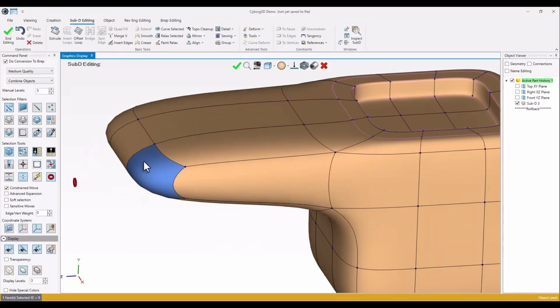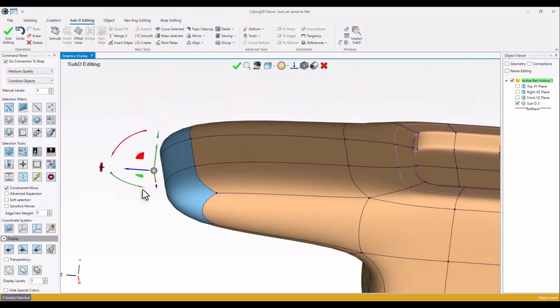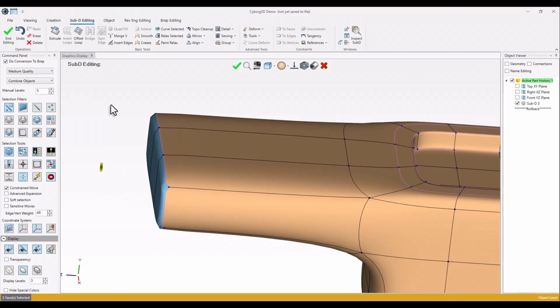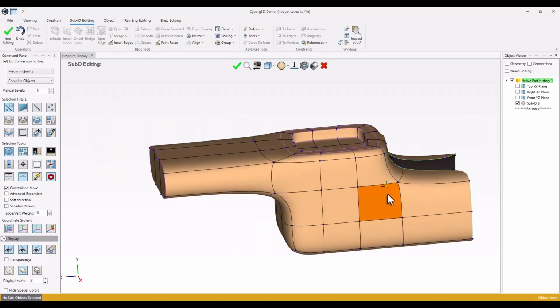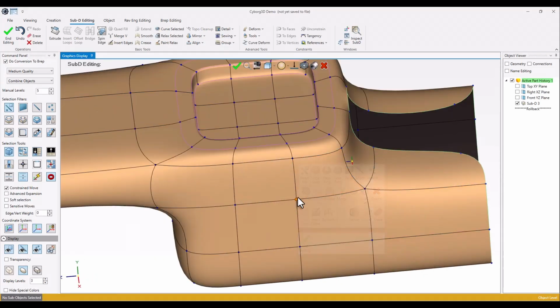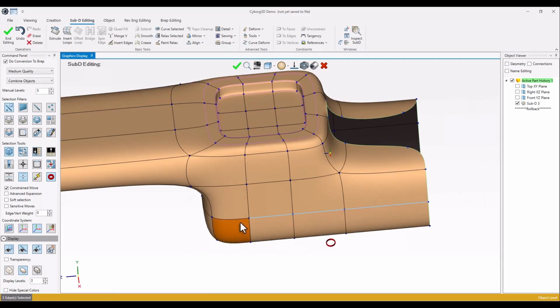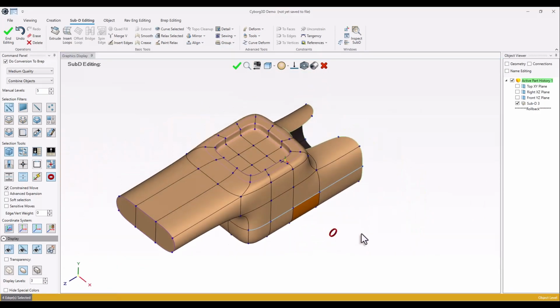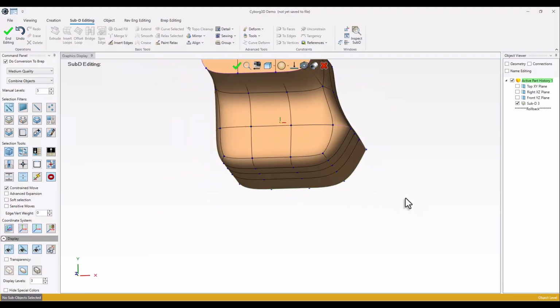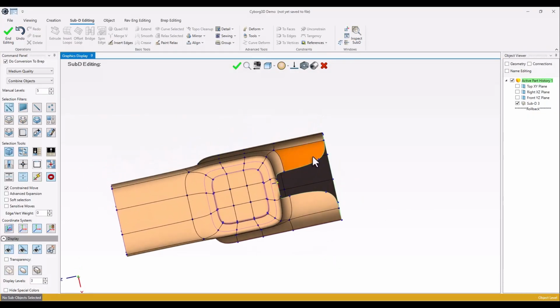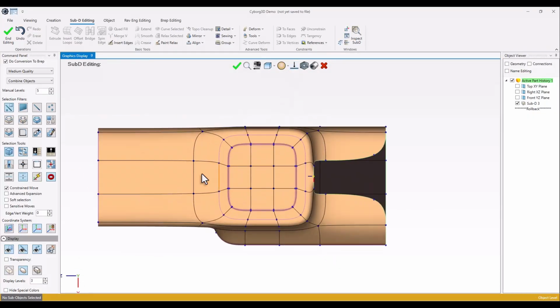Okay, so now from this thing here, I can select the faces, also doing the same thing, which I could even go to 100 crease, so that is now very flat sharp edges. Okay, same things could be done on the edges here. So I can select these edges, and I'm gonna go to maybe 70 and move it a little outside like this. And here comes our next icon, which is gonna be the mirror section.